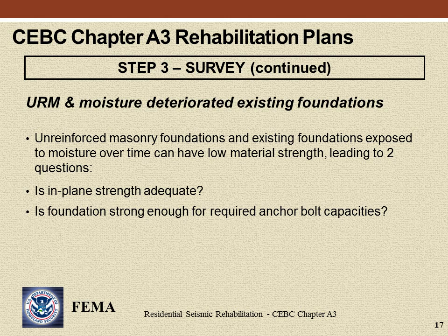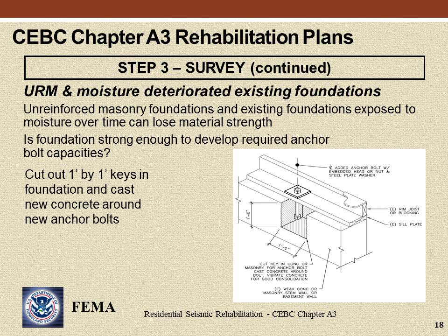ATC 50-1, Chapter 4 recommends that existing potentially weak concrete footings be tested by striking them with a hammer. Concrete that does not readily break off is considered adequate for carrying the relatively low stresses borne by the cripple walls. Where mortar in unreinforced masonry foundations can be very easily scraped out with a screwdriver, additional evaluation is suggested. Testing methods are available to verify in-plane strength of masonry where adequacy is of concern.